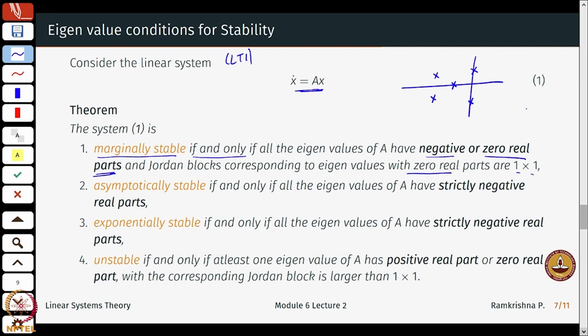So what does this mean? If I have poles of the form plus minus j, like repeated poles on the imaginary axis, this system turns out to be unstable. You can check for this condition. Earlier control lectures of basic undergrad control engineering would tell about this. If there are repeated poles on the imaginary axis, then that leads to instability.